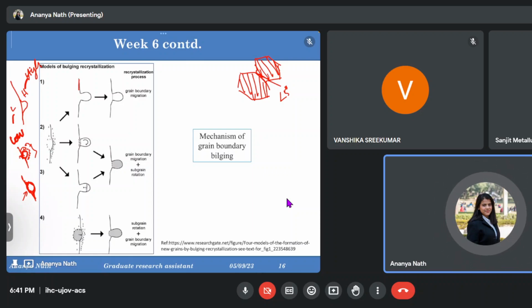It's happening abnormally, because we assume that we'll be getting some dislocations only, but at the end we are getting some recrystallized grain. So this is why it's good for us. We don't have to go for the elevated temperature now, but still it's an abnormal thing for us, because this is not the right time for them to give rise to these new grains, but it's happening.